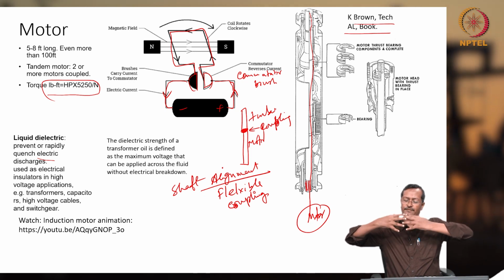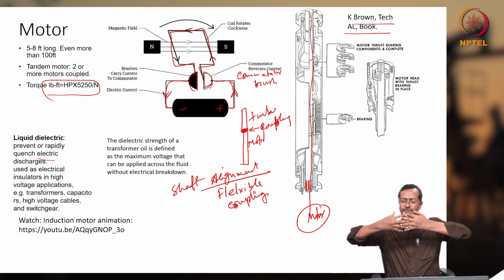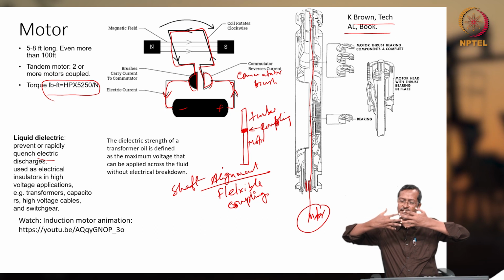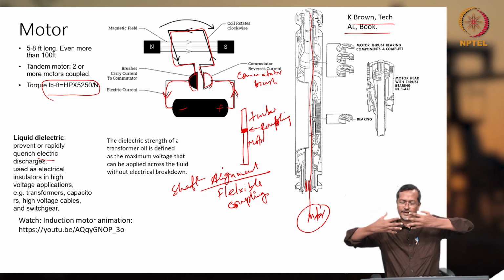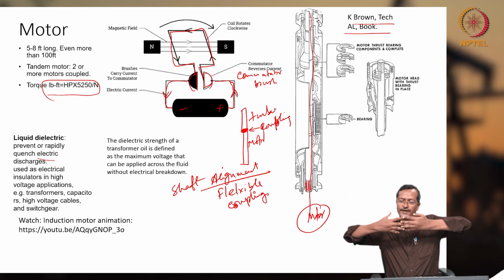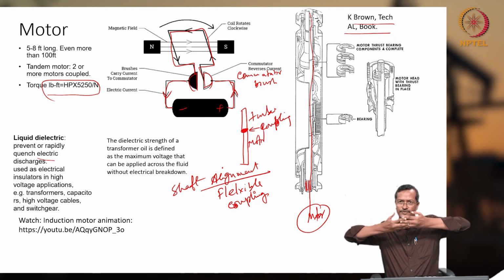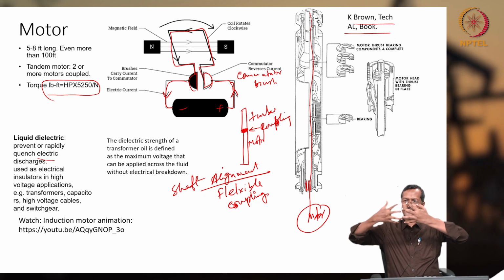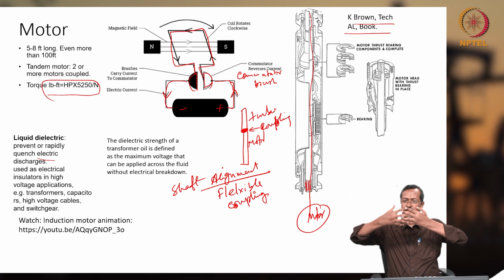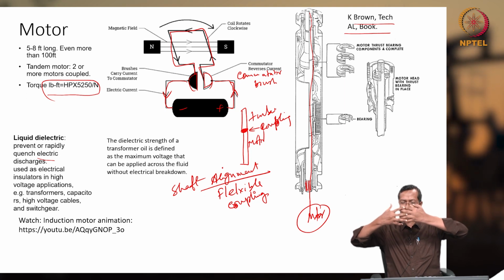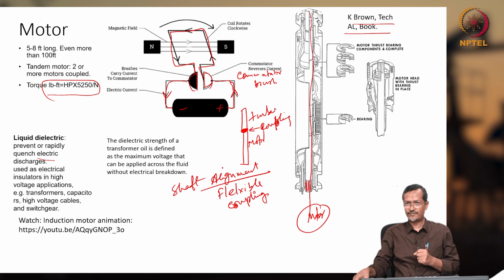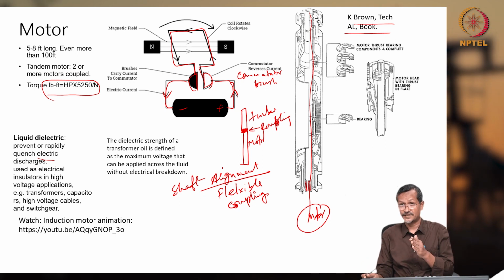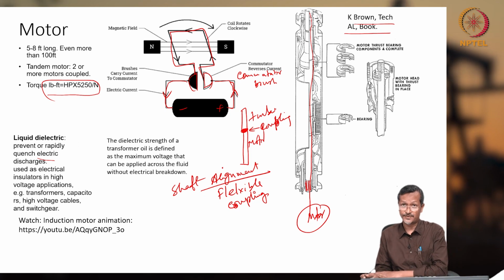For example, my shaft one end is here, another end is here. Okay. So, if there is any axial movement, I have space here because of this axial movement. So, any axial problem here will not be transferred, and it will still be rotating because of this specific shape. Again, you have to give some sort of flexibility, like it is not tightly fit like this. So, if there is any misalignment like this, it will also be no problem. So, that is why we give a flexible coupling in between shafts, so that no vibration will be transferred, no extra axial load will be transferred, no misalignment.